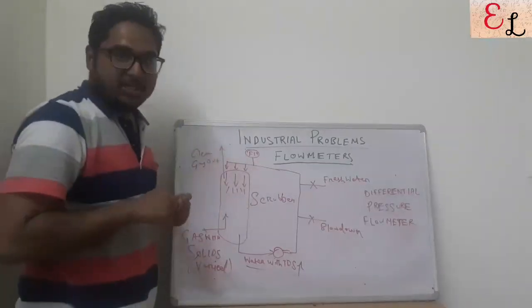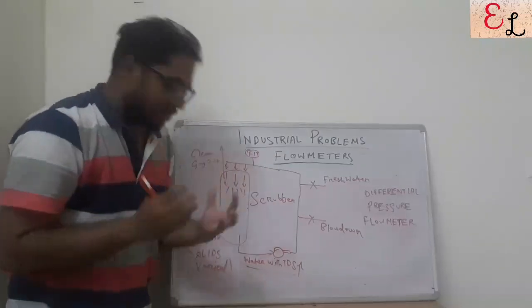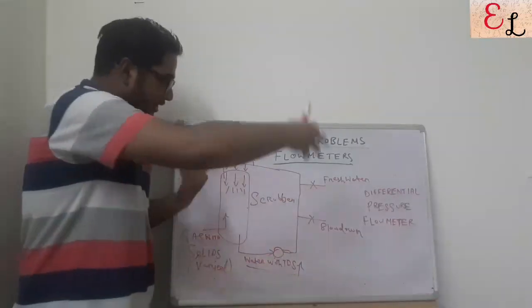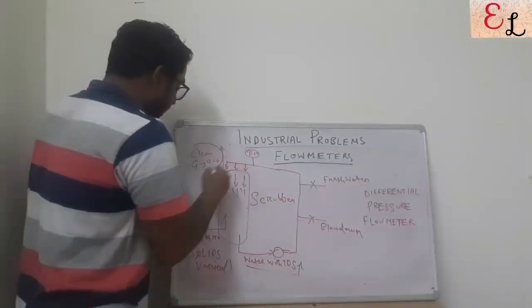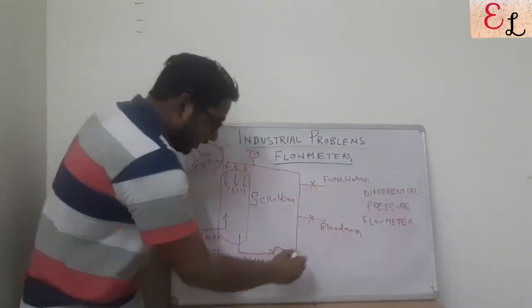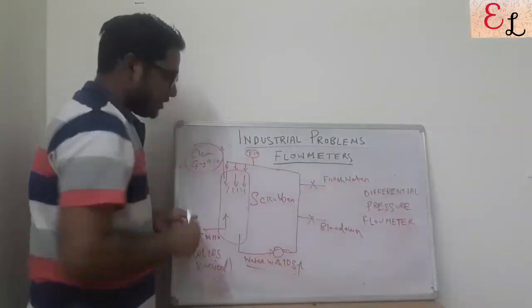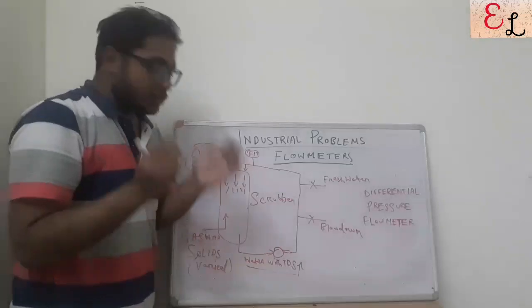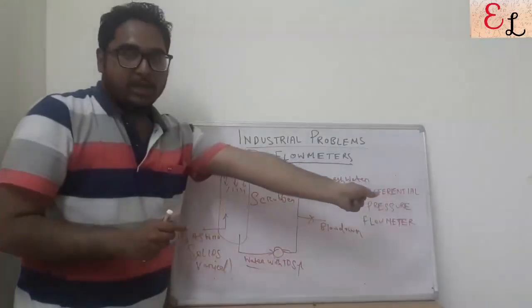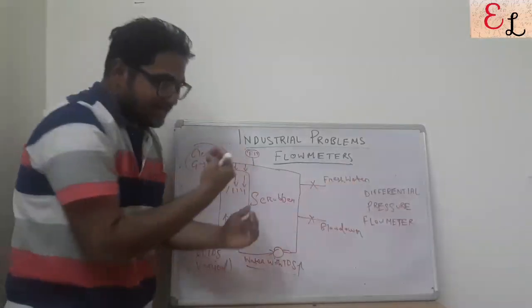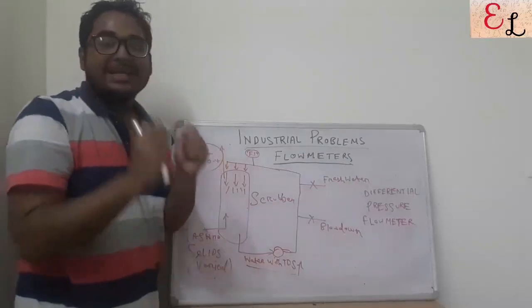It depends on the application that it is put to. Sometimes it is coming with a high dust load, sometimes with a low dust load, and the circulating water is taking the dust out of the system, and a clean gas is going out of the system. The water with the TDS, the dissolved solids within the water, is being recirculated in the system. So there is a slow build-up of TDS throughout, and at times we blow down some portion of the liquid and replace that same amount with fresh water to maintain the TDS in the system.